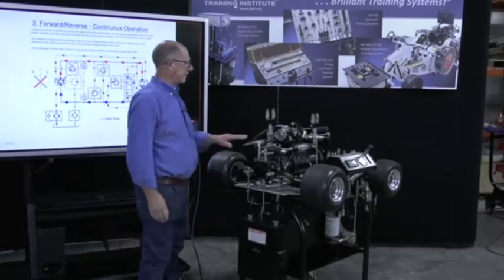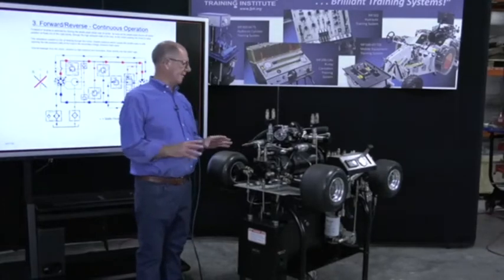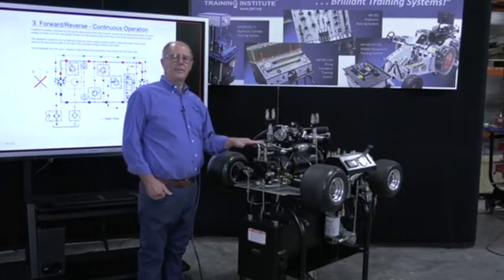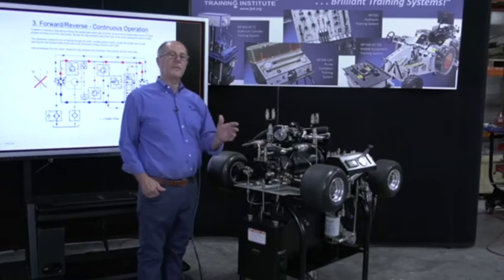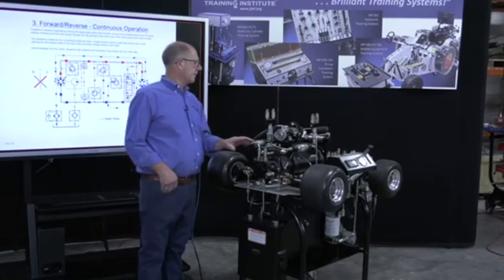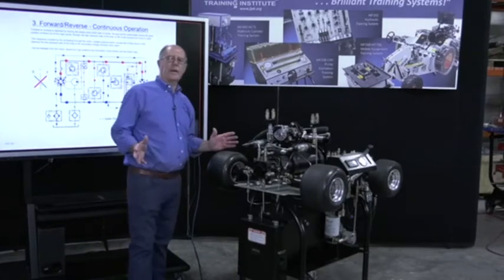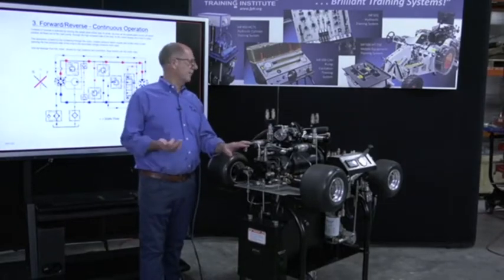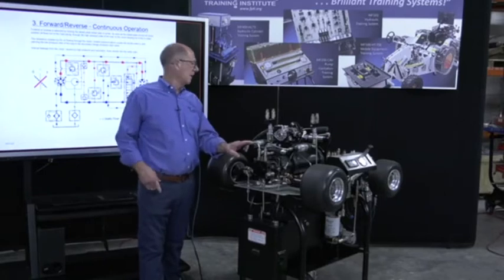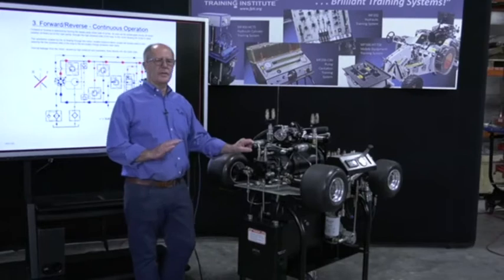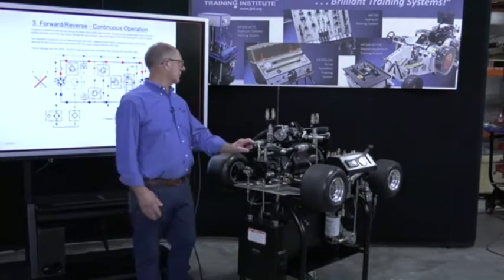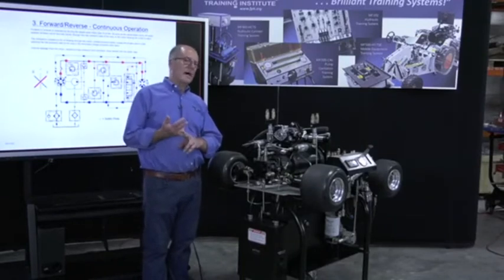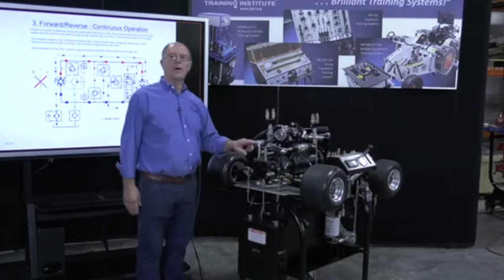All right, so just for those folks who are not totally familiar with the layout of a hydrostatic transmission, I'm going to use our VCLS 300 to show you exactly what I've just covered in our presentation. What you're looking at here is a 2-in-1 trainer. The rear end is full hydrostatic drive, and it's a light-duty transmission for good reason, because this can run on a 115-volt circuit. The front end has the same steering as any articulated machine, meaning it's got a steering orbital valve, cross-port reliefs, and a priority flow divider, so we decided to just make this a 2-in-1 trainer.